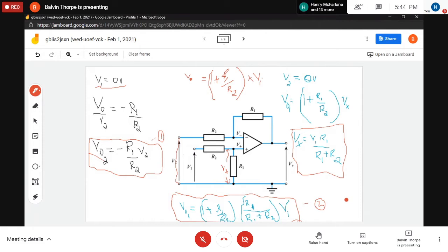All right, so now we have the 2 equations based on output voltages from the 2 input voltages. And superposition says what you should do with them? Sum them. So we have equation 2 and equation 1. Therefore, the total output voltage is VO1 plus VO2, equation 1 plus equation 2.